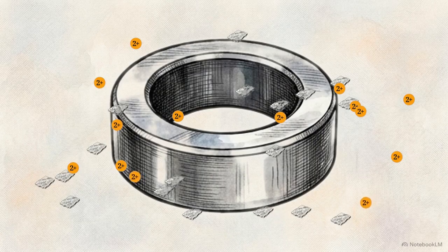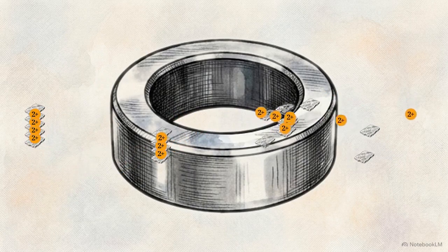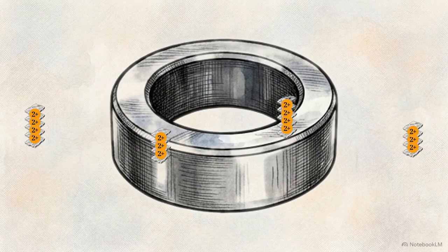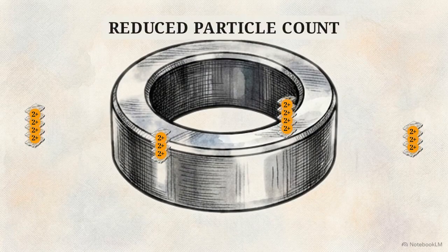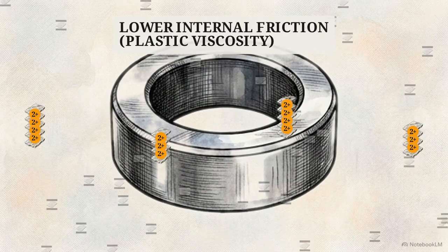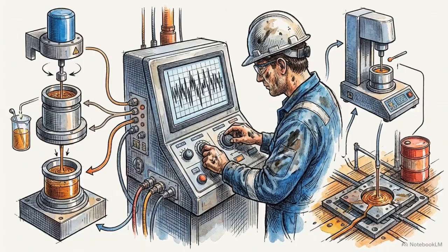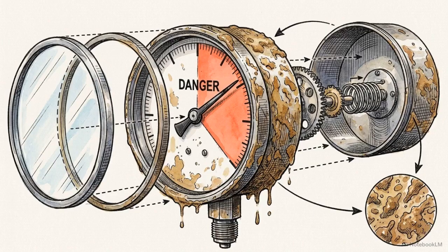This diagram shows aggregation, where divalent cations, such as calcium from cement or anhydrite, cause the plates to stack face to face. Stacking the plates thickens the individual packets, which reduces the total number of independent particles in the fluid and eventually causes the viscosity to drop. Every rheological change observed at the surface is a direct reflection of these specific association states shifting and reforming in real time.